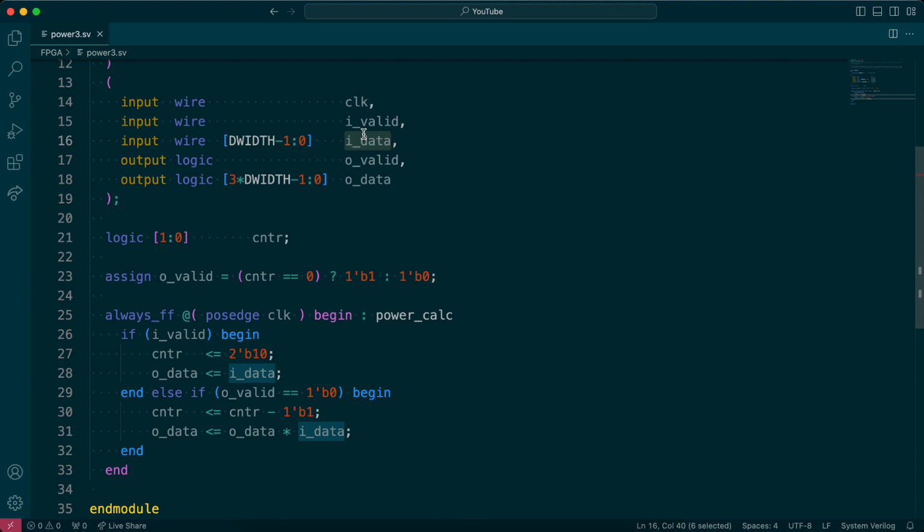So if there was a way that I could save the previous values as the new data comes in, then I could process more data back to back. This is the concept of pipelining, right? So the data keeps coming in, like you get new data every clock cycle, right? And then you save it and you deal with the saved values. And then after 3 clocks, you can just update the saved values. Okay, let's see how we can do that.